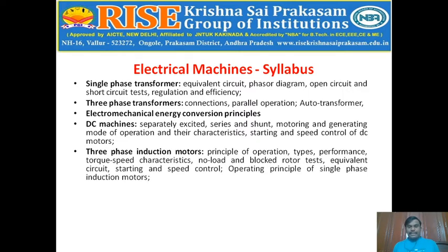From the three-phase induction motor point of view, what is the principle of operation, and what are the types, such as squirrel cage and slip ring motor? What is the performance, the speed versus torque characteristics, the no load and blocked rotor tests, and the equivalent circuit diagram? It is also known as the rotating transformer. Then the starting methods for the three-phase induction motor, and the speed control techniques, such as V/F control, etc.